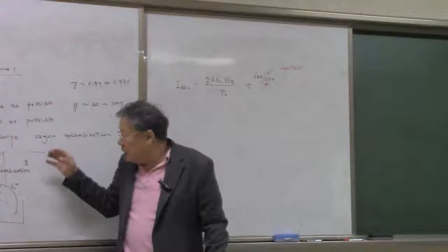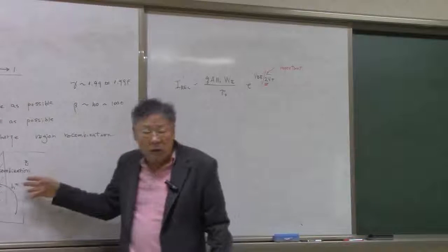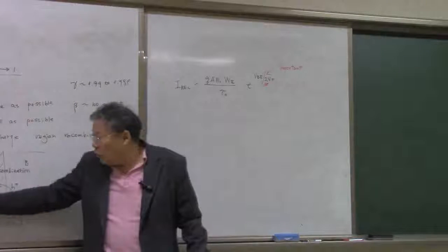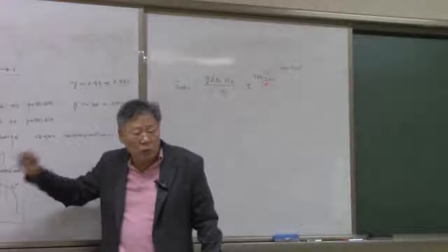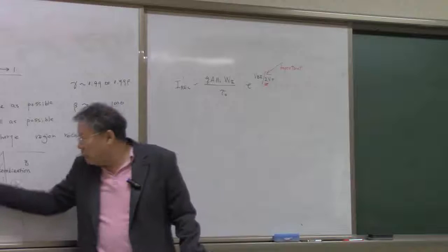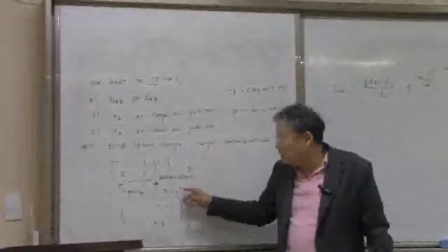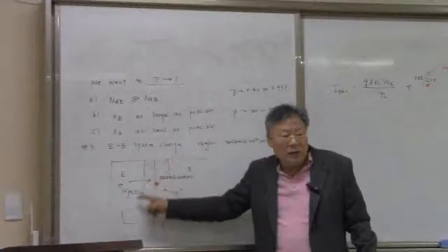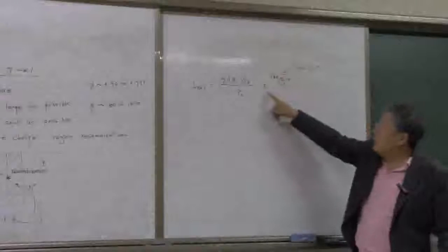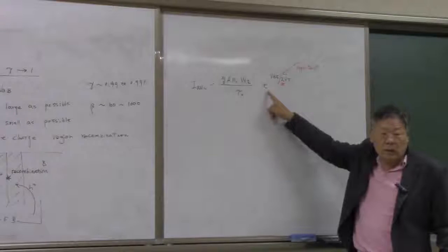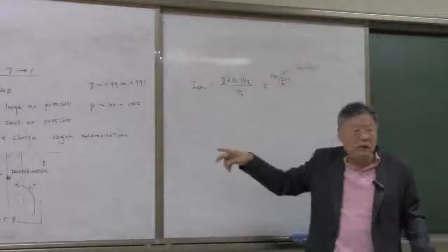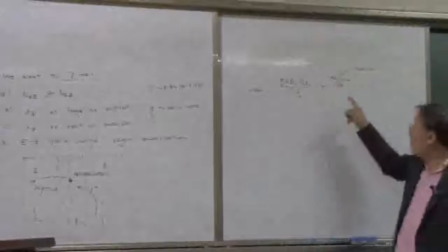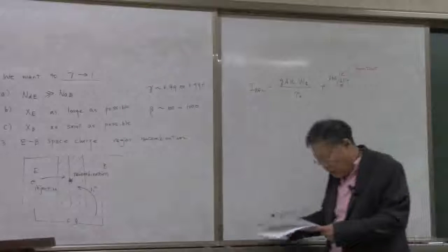So this recombination is related to the hole generation and the electron generation, two things. The electron injection or hole injection alone, we have just VE over VT in the exponential, right? But this recombination happens by those two factors at the same time, so that we have the factor 2 there.